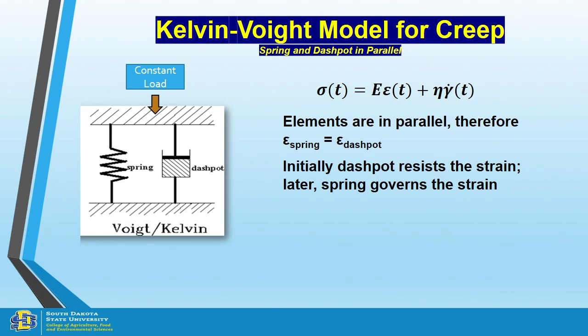The other way to explain it is, let's say this is your food material, you just need to put a weight on top of that. When you put the constant force here, you monitor how the deformation is occurring. As soon as you put it there, it will not instantly go. It will slowly go down. So that's what you are monitoring, the deformation with respect to time. That's what creep is all about.